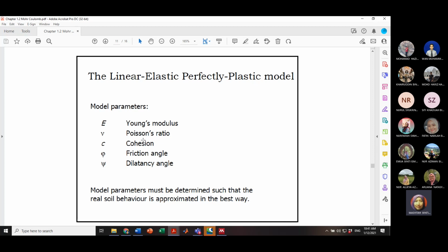So when you want to study its force behavior, the tension force or any forces that exist, it's not easy to take into consideration by just replacing it using the Mohr-Coulomb. During that time, maybe Mohr-Coulomb is not applicable anymore. So you need to figure out which other model is suitable, for example Drucker-Prager, or the combination of coarse and fine grains such as silty sand. So maybe other advanced models can be adopted in numerical modeling and simulations.